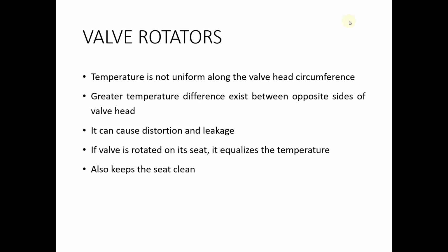Valve rotation also ensures that it equalizes the temperature and keeps the valve seating clean, because especially for the exhaust valve, the exhaust gases passing through contain carbon and other deposits, and these will accumulate at the valve seating as well as the valve head.